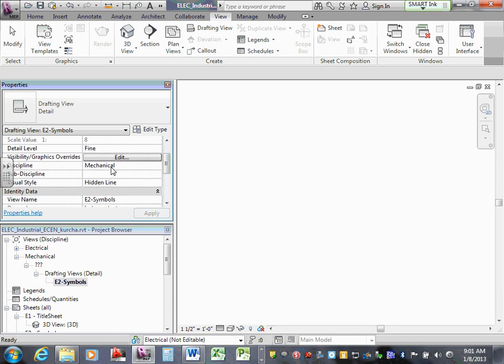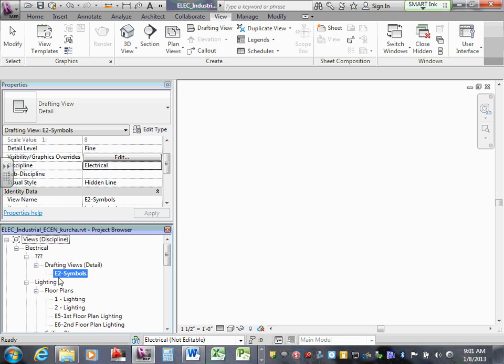Can you guys see it when you click? Everybody found it? It drops the view for you, Gary, under mechanical. It defaults to mechanical. So just click on it and click on mechanical here. Everybody can see that under property, and change this one to electrical because we don't want to care. And shift it all the way up under electrical. Can I have thumbs up that we know where drafting views are and we shifted them, guys, to under electrical?